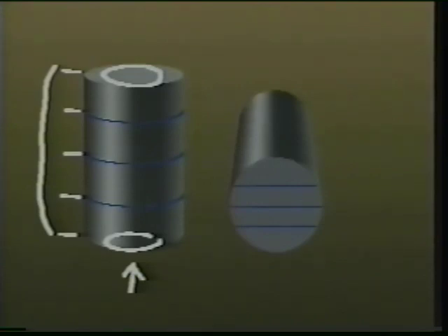If, however, we were to place the tank on its side, we would no longer have a linear change in tank level due to the constantly changing surface area, which would increase as the level approached the wider dimensions of the tank, and then begin to decrease as the tank narrowed out.